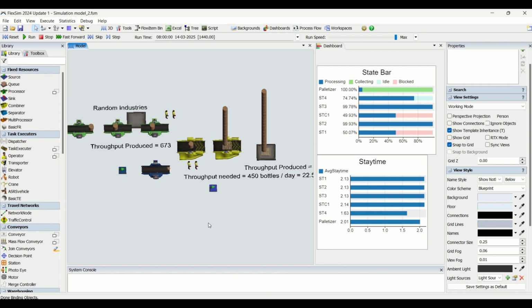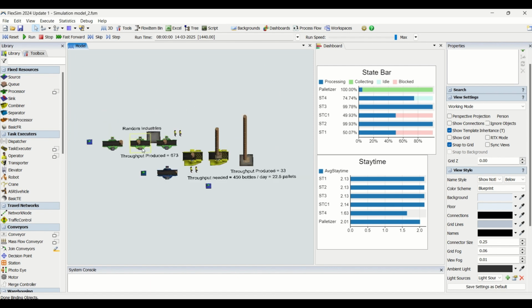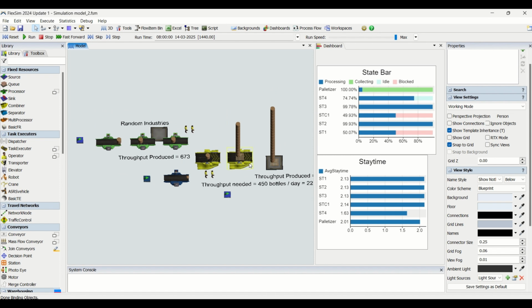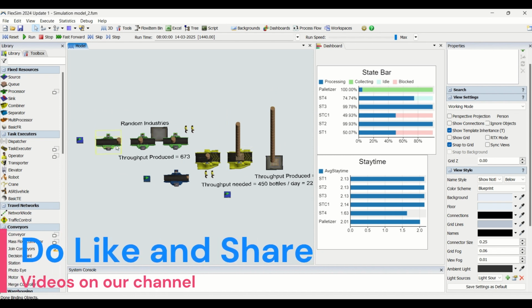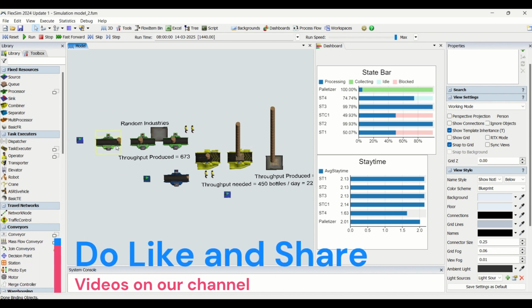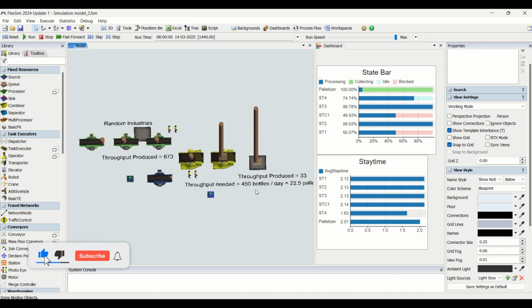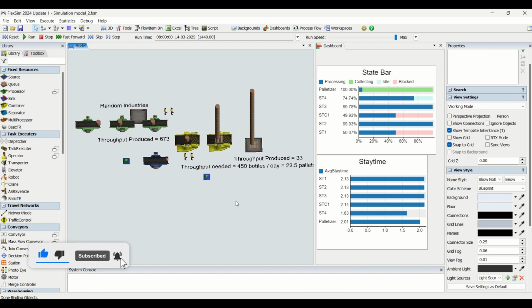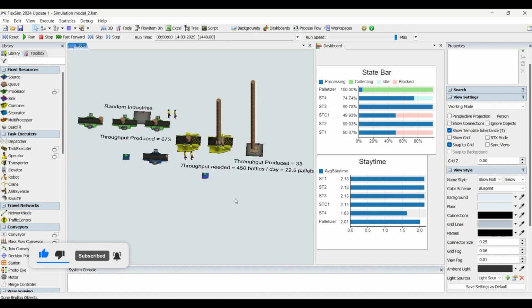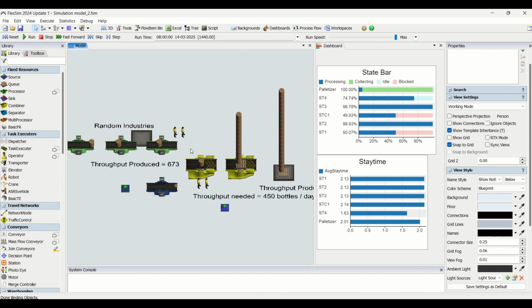So that is what we have found out, that if our cycle time is more than 2 minutes into the system, we are not going to meet our targeted demand. So the takt for the line needs to be under 2 minutes per bottle, right? So that is the finding for this 2 days simulation case study. So we are able to debottleneck the systems.